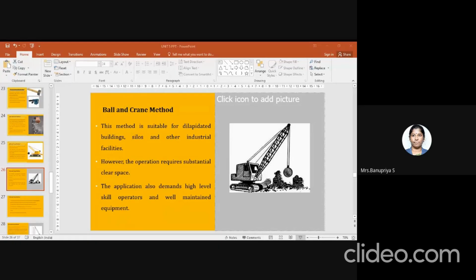So in pressure bursting, what they do first, for example, if you want to demolish one particular floor or wall, is drill some holes. Whichever component you are going to demolish, they will do the drilling work on that component, at equal intervals, using drilling machines or drilling tools.